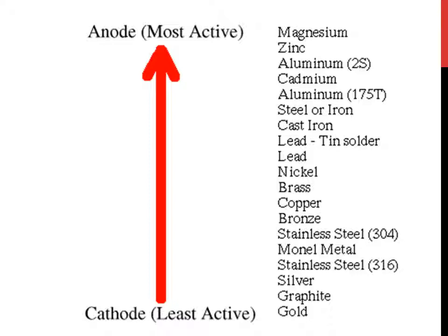Under a conducting medium, in the presence of environmental conditions, maybe the presence of electrolyte or moisture, there will be generation of anodic and cathodic areas on the metal surface. Hence there will be formation of a tiny galvanic cell on the metal surface.